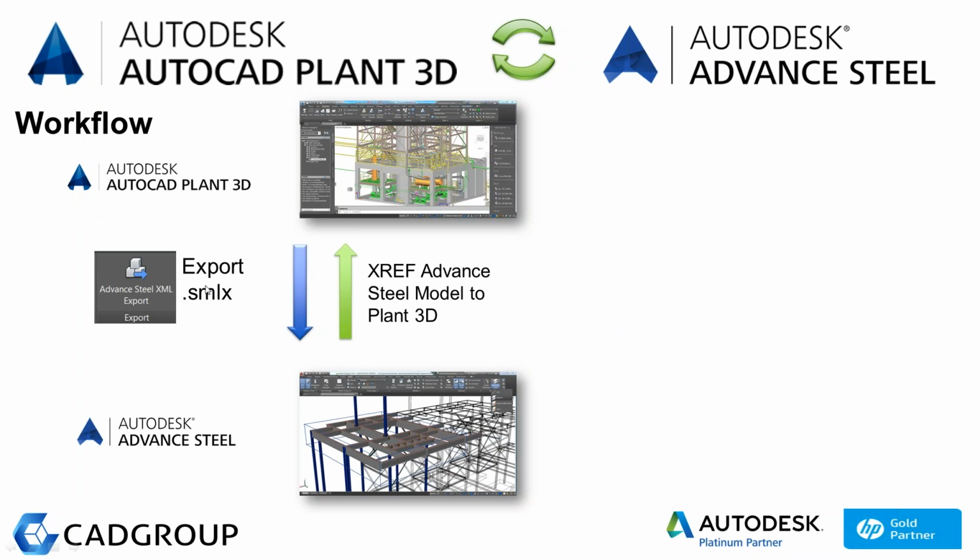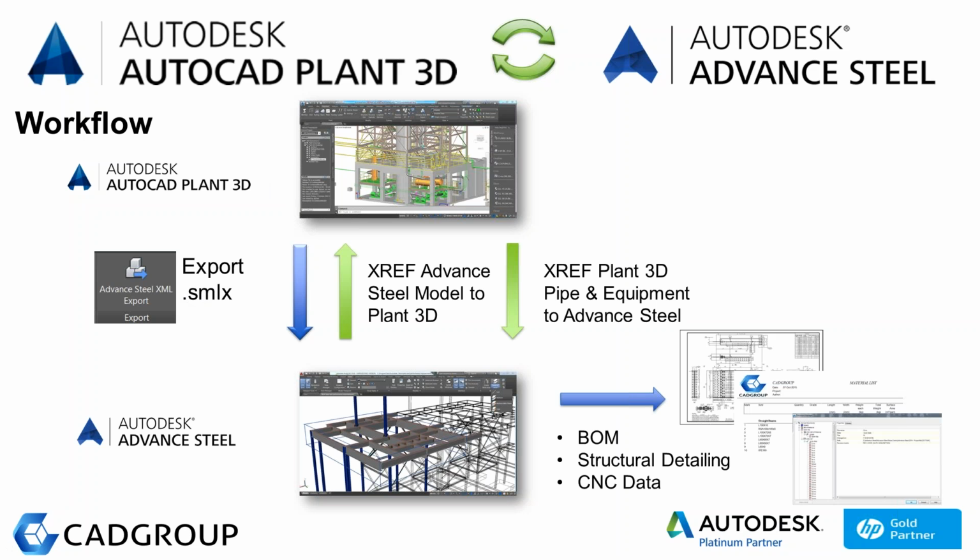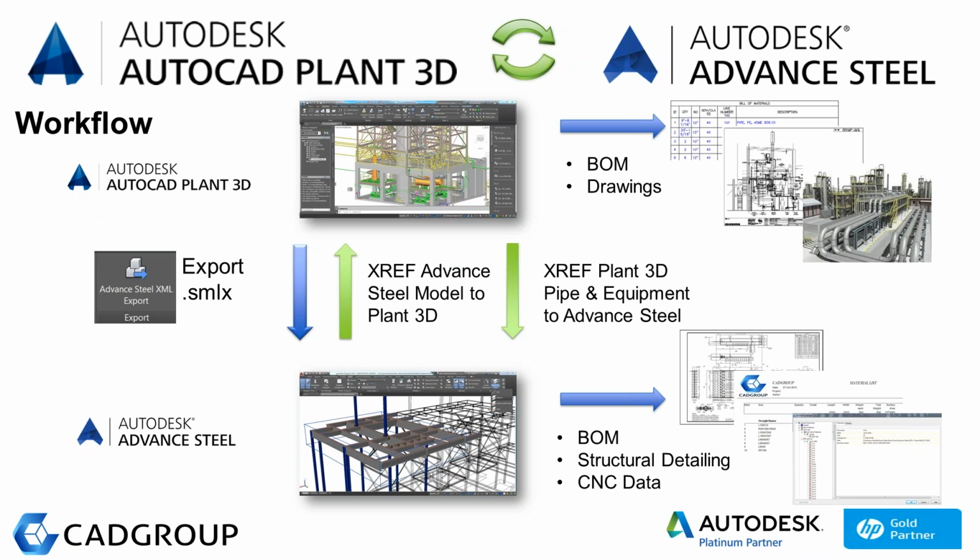But also, being both AutoCAD-based applications, we can XREF Plant equipment that's been drawn up in Plant 3D back to Advanced Steel, so we can also check for clashes in a bidirectional workflow as well. Okay, so from Advanced Steel, we can then look at all our structural detail information, our bill of materials, our reports, our shop details, and so on. And all that information can also be incorporated into the drawing information for Plant 3D.